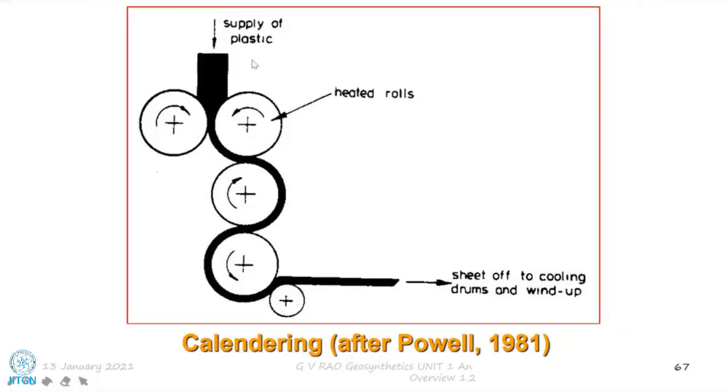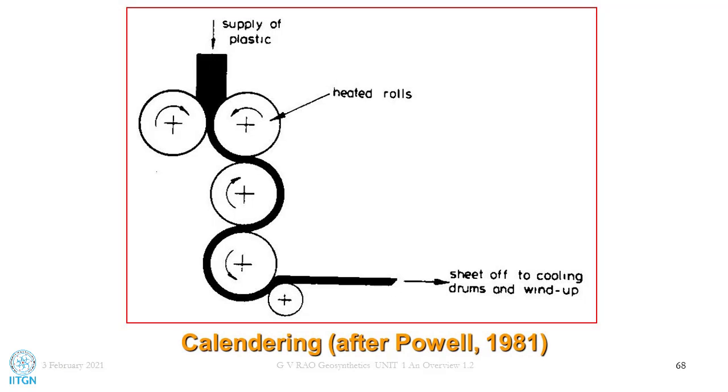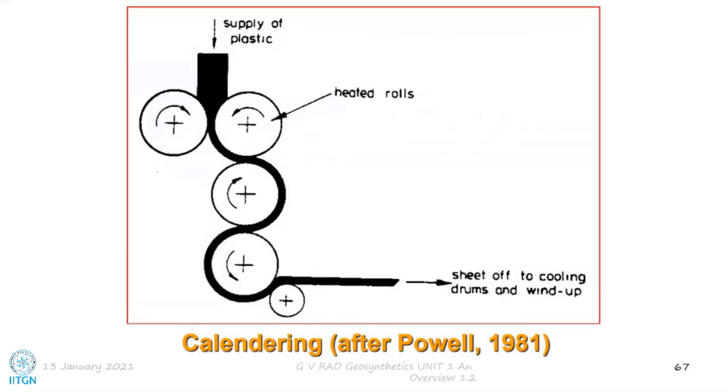So in this kind of system, that is the calendering system, we supply plastic under hard conditions, it is passing through hot rollers and getting some thinning down, and then it is compressed in further rollers such that it is going to become thinner and thinner to the requirement we make. So this is definitely happening in a more controlled condition, which makes the quality. So we can have both calendared, which is good, and also air-blown, which is good, and processes are going to vary depending upon the actual polymer we are going to use and additives which are going to be there.